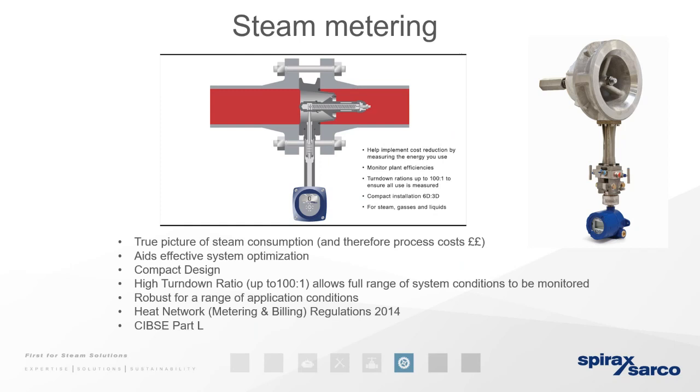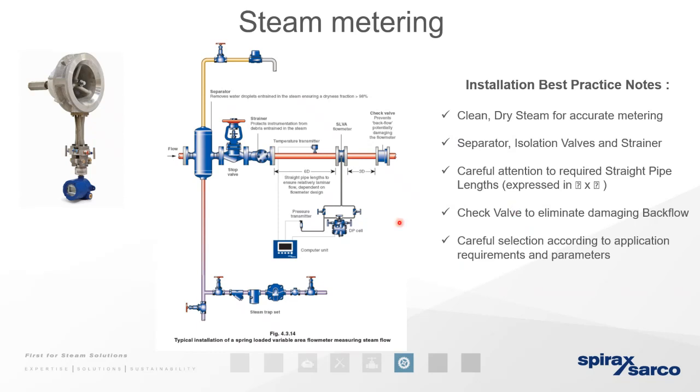But installing the steam flow meter requires a couple of things. It's not just a meter that I would put in a steam system and hope that it will last. We have to ensure that we provide this steam flow meter with dry quality steam. And as we said a little bit earlier, the way we would want to do that is by means of a separator. A separator will eliminate any entrained moisture within your steam system or any carryover from a boiler, and therefore protect your isolating valve as well as your flow metering system, ensuring good quality steam and therefore also ensuring accurate metering.